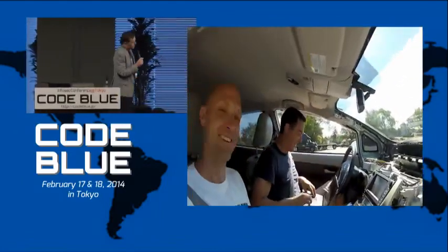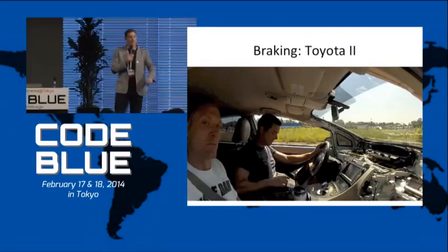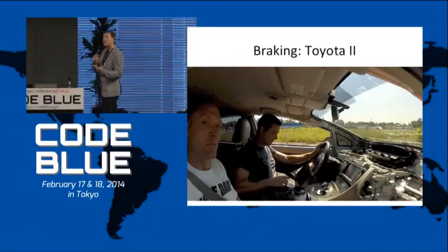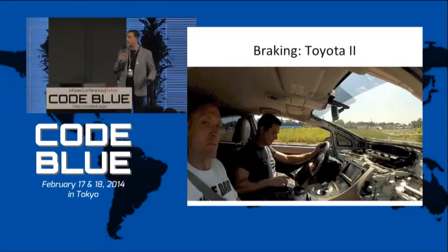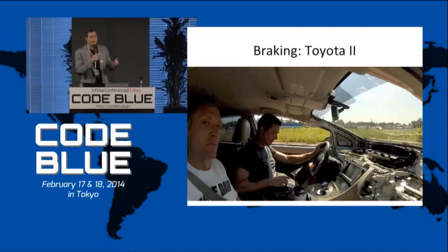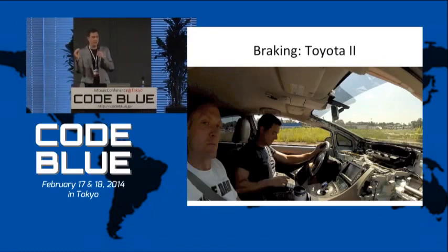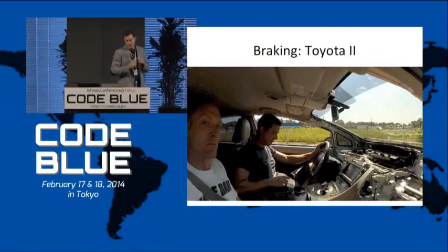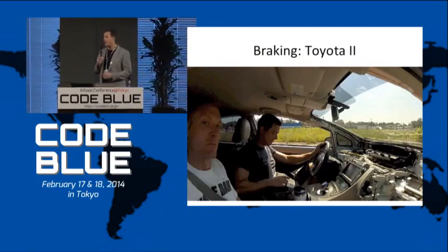So we're braking there by telling the car, hey, you're about to be in an accident, you should press the brakes. And it clamps the brakes. And you can actually give it a percentage that you want to clamp. Sometimes it'll slow you down. Of course, we put it to 100%. As long as we played that message, the car could not move. Because the engine wasn't powerful enough to move the wheels once all the calipers were shut. So again, it's neat to know that you could completely immobilize the car just with its own brakes.